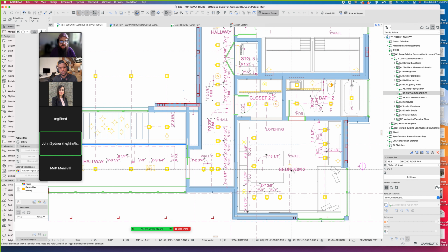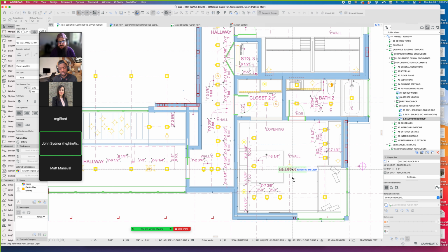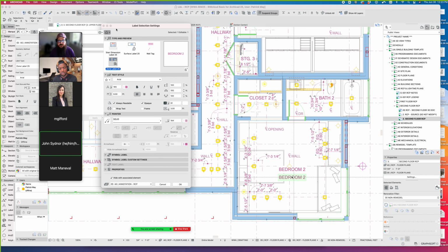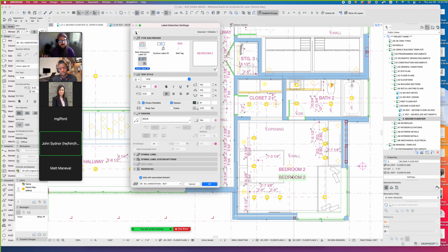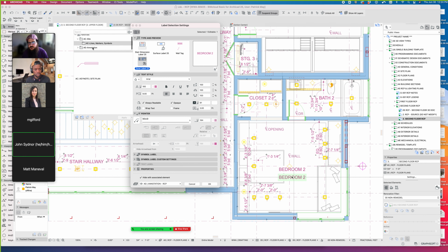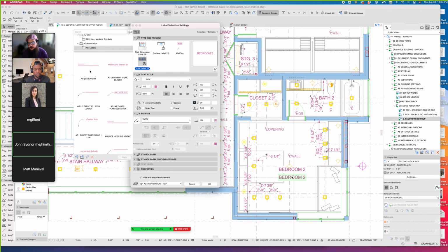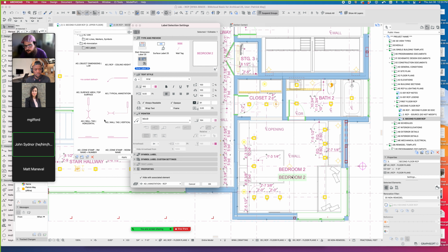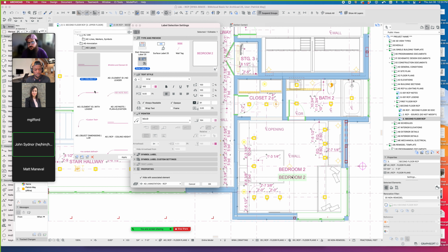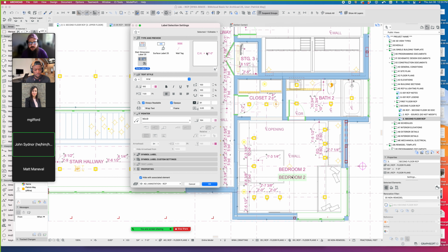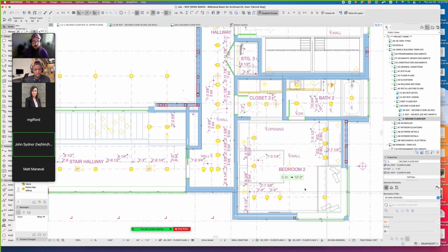Yeah, so the zone stamp here, if for example I wanted a zone or ceiling height in this room, I go to the settings, the current template, and this is actually pretty recent, so unless your project started in the last 2 weeks, you probably won't have these favorites. But the current template includes favorites under annotation labels for ceiling height. There's zone stamp room name and number, and then there's ceiling height. And they're all using the zone stamp. So here, for example, this says ceiling height 12. That's pulling from the actual height of that zone.